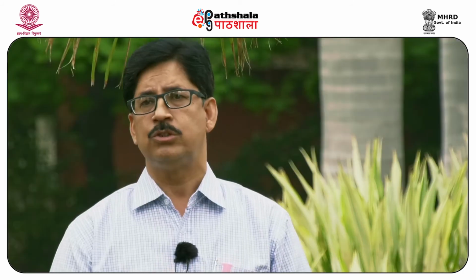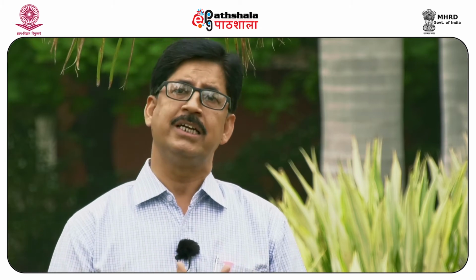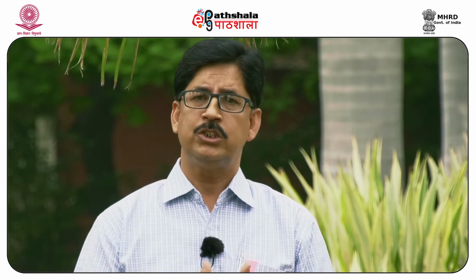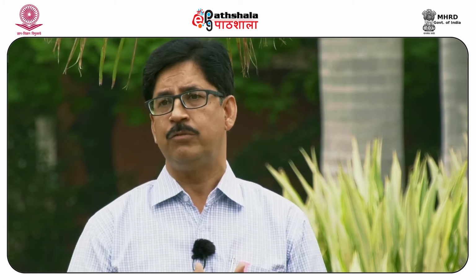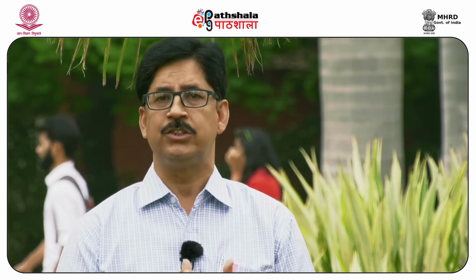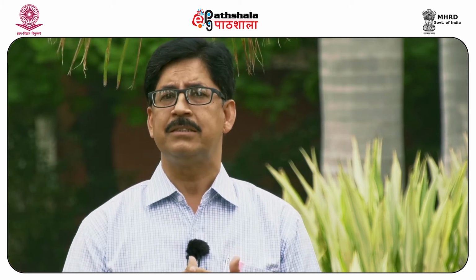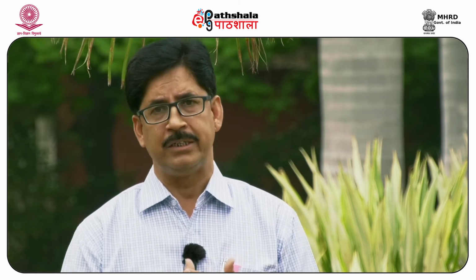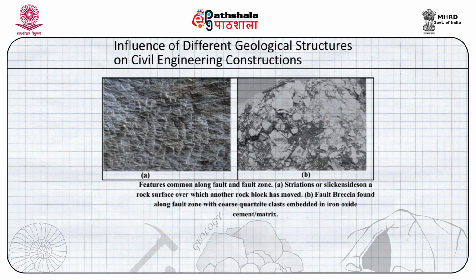There are various methods to work out the antiquity of a fault. Those are the geophysical and geochemical methods. Once you are sure enough that the faults are active, then we should first try to realign our structure, because active faults can always result in movement. Along the fault also we find gouge, mylonite and breccia. Because of movement along the two fault planes, the rocks are crushed.